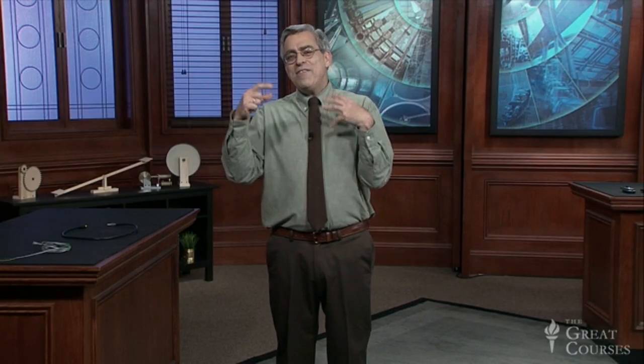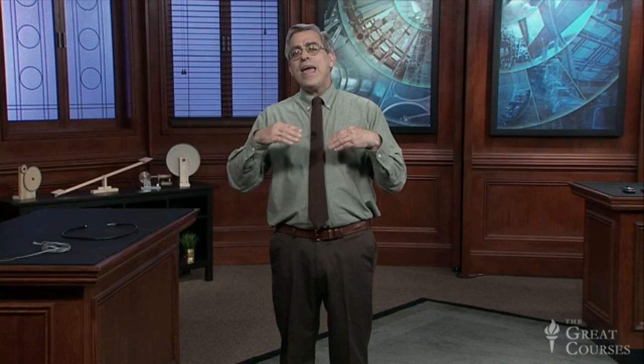The problem is that an amplifier can only increase the power of the signal. It can't remove the noise. Indeed, an amplifier actually amplifies the noise right along with a signal, and even adds some internal noise of its own. Thus, noise accumulates throughout the transmission, and because there's no way for the receiver to distinguish between signal and noise, errors are introduced into the transmitted information.